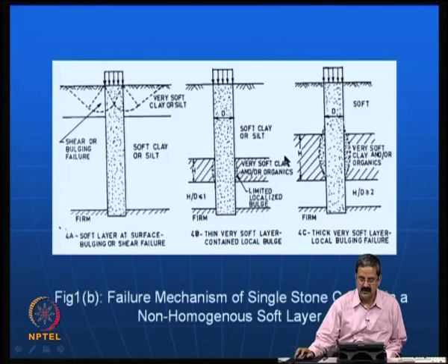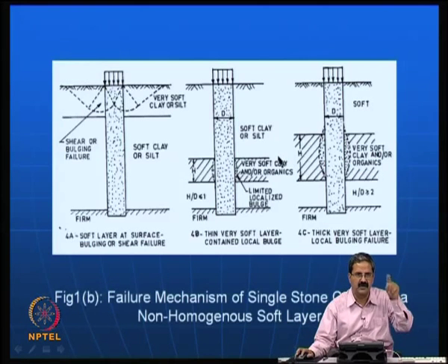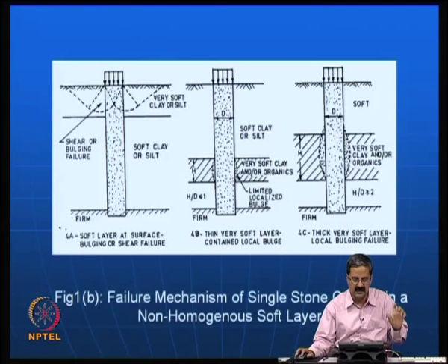So, one should look for proper soil investigation and take care of these particular points. That is what you see sometimes in SPT, CPT profiles. If in some places you have weaker values obtained, it means the confinement was not really good there.